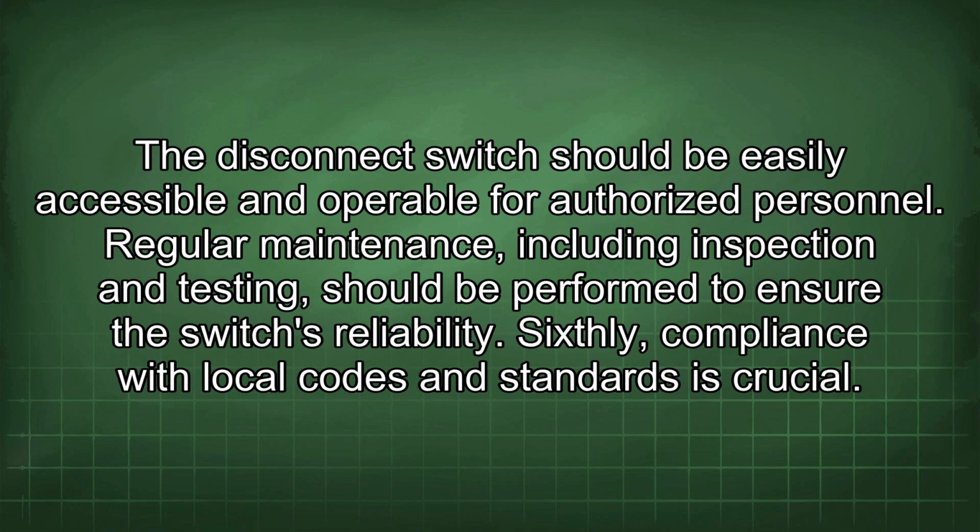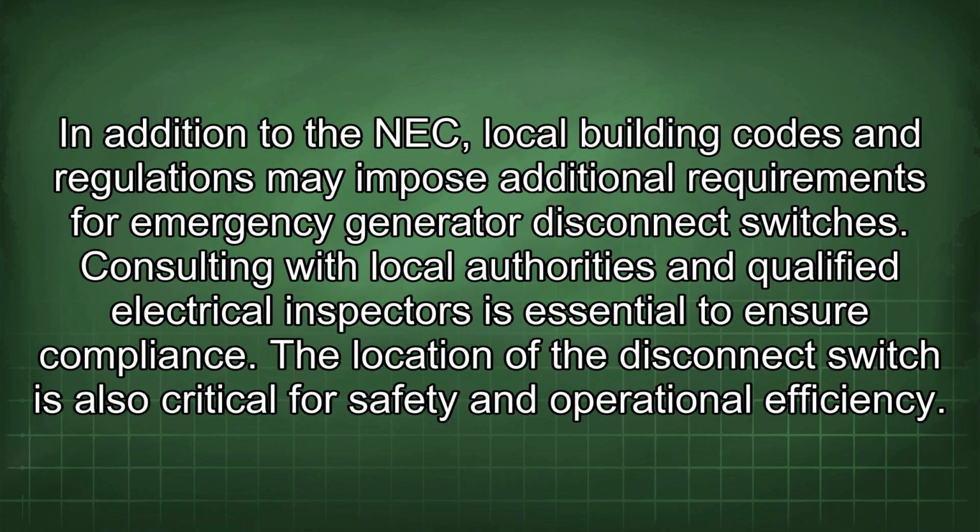Regular maintenance, including inspection and testing, should be performed to ensure the switch's reliability. Sixthly, compliance with local codes and standards is crucial. In addition to the NEC, local building codes and regulations may impose additional requirements for emergency generator disconnect switches. Consulting with local authorities and qualified electrical inspectors is essential to ensure compliance.